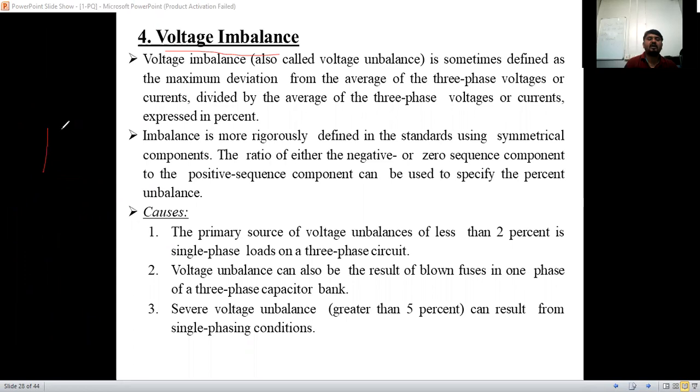We are getting 3-phase supply, so all the lines are phase to neutral, and I will use the neutral line here. So the loads should be distributed equally. Whenever you design house wiring and all, you have to think of this. The load should be equally distributed across all the phases. Suppose you have a 3-floor building.